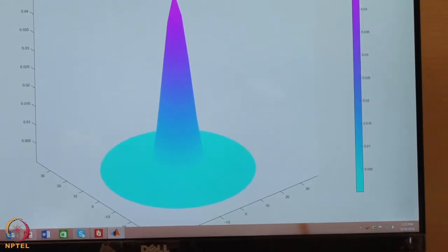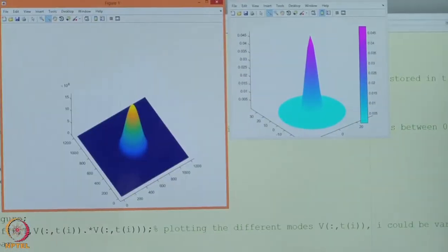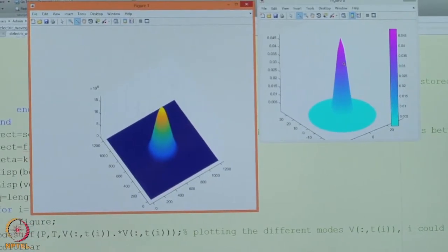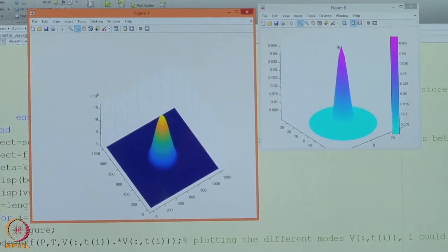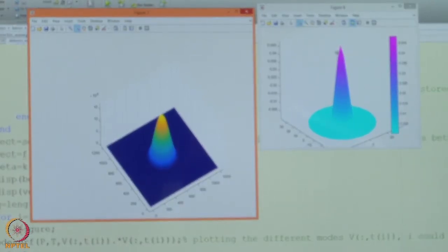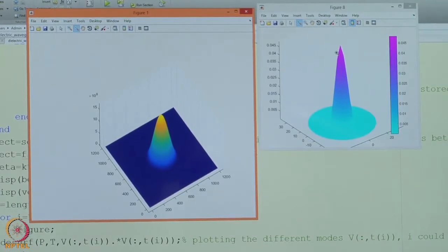So could you please explain how you understand or why you see this discrepancy? Here the meshing that we have taken is coarse. So due to that, we are not seeing the complete smoothness in the tip, but maybe we can find it if we use a finer mesh. We will show that later.